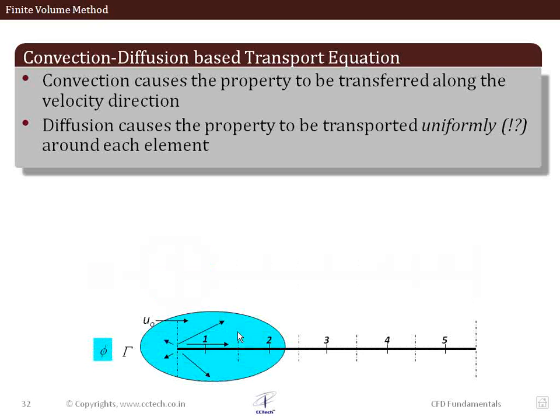But usually what we encounter is a combination of both the convection and the diffusion terms. So we need to give more account to the value at a face. We need to give more preference, or at least a bit more preference compared to the cell downstream. We should give preference to the cell which is upstream, and that's why we get these schemes called the upwinding schemes.